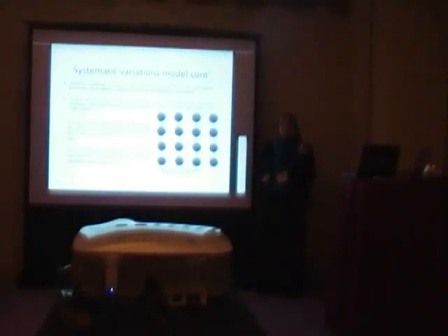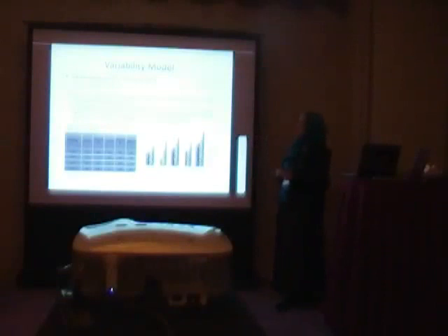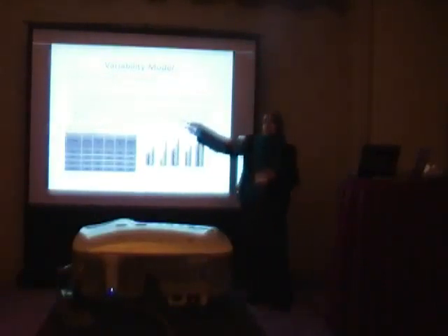We use it to calculate the delay at this link, and this link, and this link. And then we calculate the deviation of different delay values across the node. Thus, we get a systematic component with mean and standard deviation for the delay. Okay. The total deviation in the delay will be the sum of the random component and the systematic component.